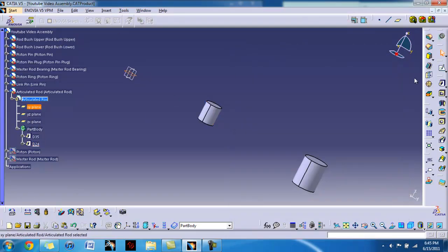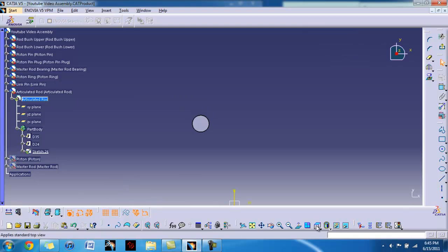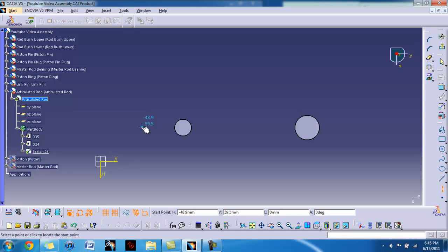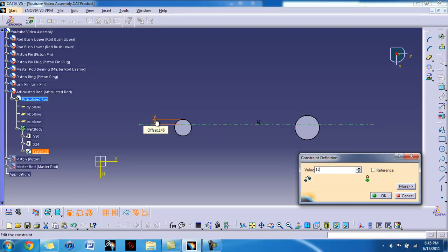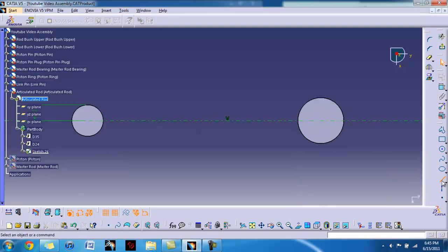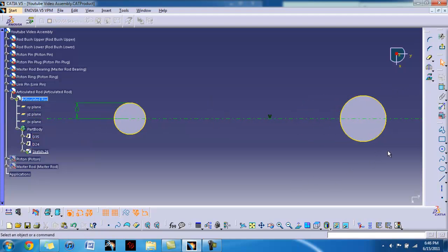Alright, going into your XY plane again, into top view. I'm going to create another axis system going through the center. So you can constrain that. The diameter is 24, so this will be 12. Alright, using your lines, well, before you do that, select both circles using the control key. You want to project 3D elements so we can use part of the circles.